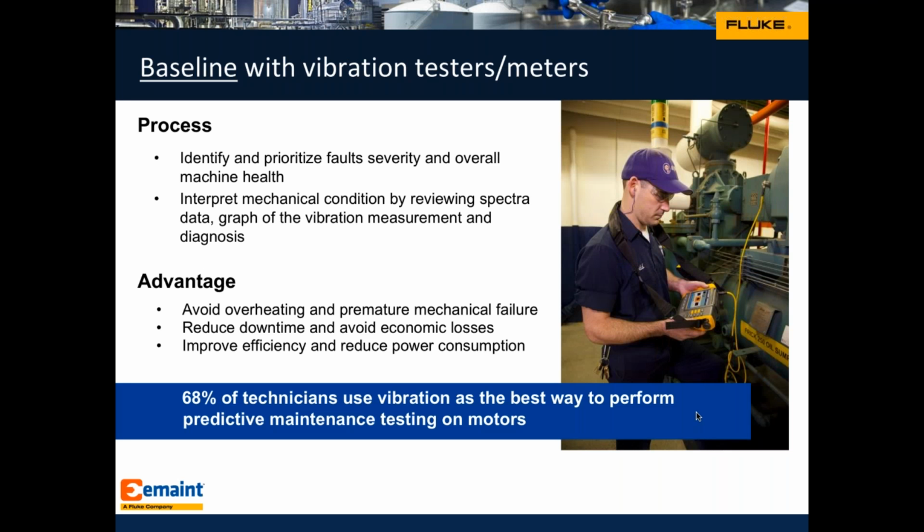Along with this, you can also do a baseline with vibration, and it could be a tester and meter. And a baseline for that could be as easy as a screening, or as complicated as a diagnosis. Most of the time, our customers will do a screening. So they'll go around with a vibration meter and walk around to all the motors, and within half a day, they have established where each of the motor bearings on the front and on the rear are. And I think that has a lot of power in order to resolve an issue.